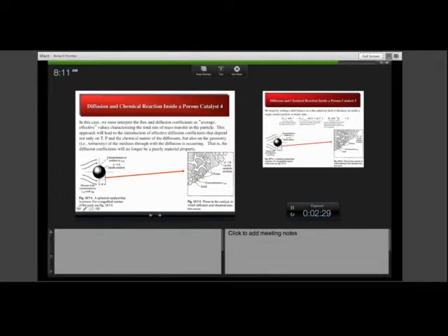And so we take another approach, which is a one-dimensional approach to the analysis of this problem, and this is the classic approach that you would have learned in chemical kinetics for analyzing mass transfer and reaction inside a porous catalyst particle.